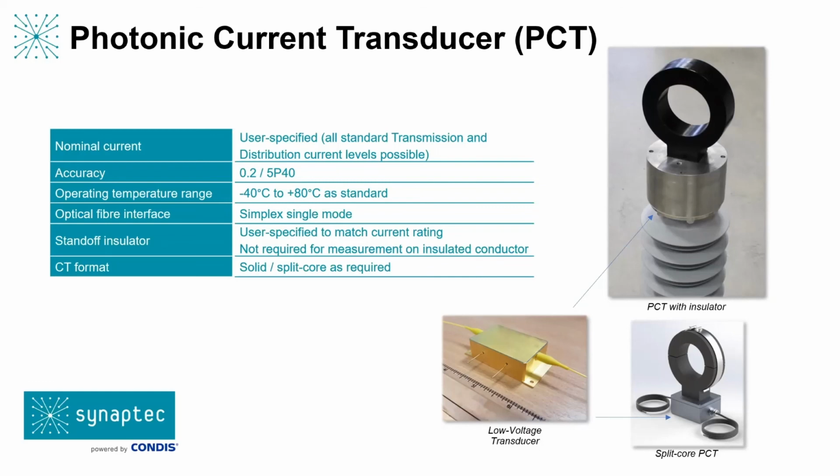So there's also a commercial application here that says if we can put a lot of sensors in a lot of places and simultaneously measure what's happening at all these points and do it safely, because these devices fundamentally are not powered and you're not using live copper wiring in the yard, that's a health and safety bonus, and it accelerates the time that the outage requires to complete the upgrade or refurbishment of the equipment.